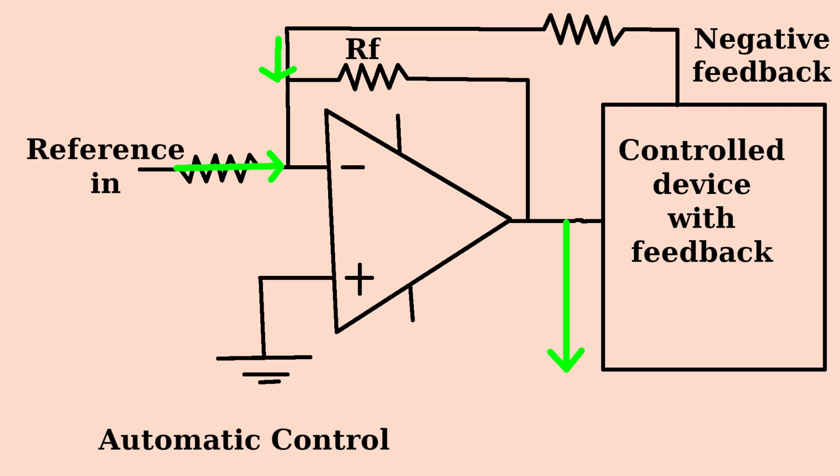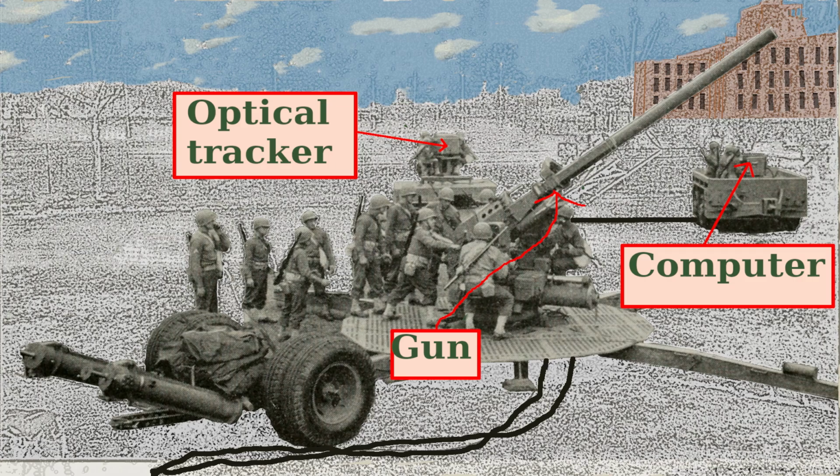The feedback resistor on the summing amp is used to control the sensitivity of the controller. Too little gain, and the circuit is inaccurate. Too much, and the circuit is unstable. This is the amplifier which developed the gun control signal for the M9 gun director.